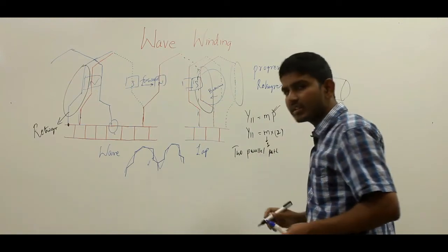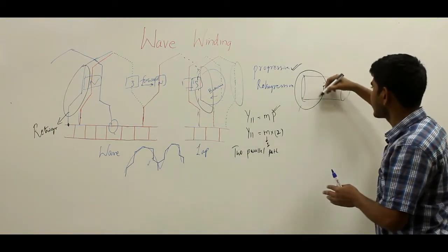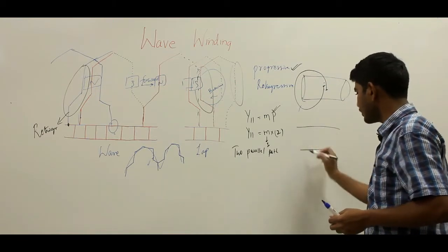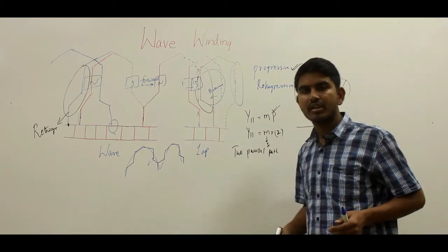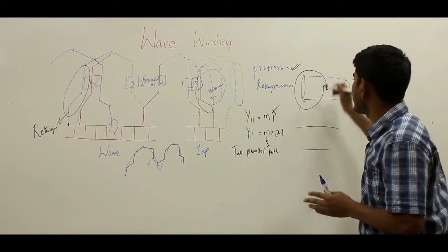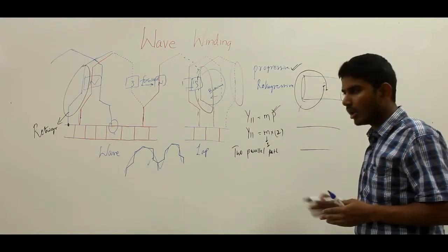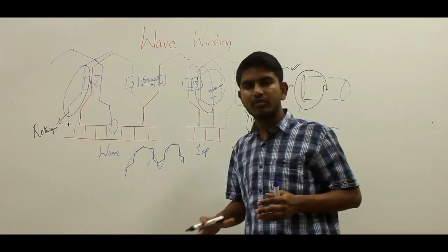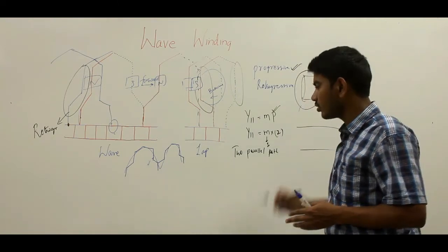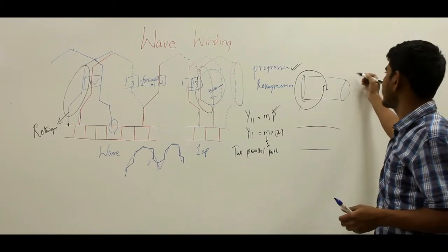having the conductors which are more or less uniformly distributed around the circumference of this core. So there will be two parallel paths, and each parallel path will have a number of conductors which are, more or less, uniformly distributed around the entire circumference of this armature core. And this uniform distribution of the conductors in two parallel paths around the armature core gives you two advantages.